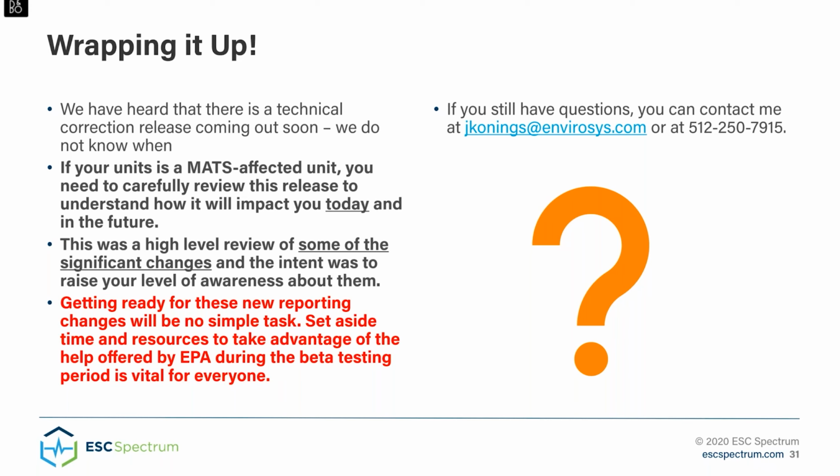And so therefore the changes that are proposed for reporting of those stack testing results will impact them. Other people use averaging plans. And so the changes that were proposed to the averaging plan reporting requirements will impact those people. A lot of people use CEM systems to either measure mercury or PM or SO2 and a diluent system as a surrogate for acid gases. And so the changes that were proposed back in September will, as I kind of described, impact them.